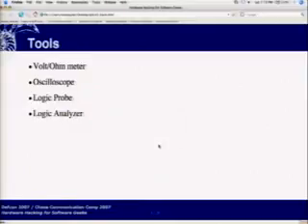So these are some basic tools that I use in doing hardware work. The voltmeter is basic. If you don't have one of these, chances are you're not really doing a lot of electronics. An oscilloscope, a little less basic, but if you get one, you will not believe how useful it is, and you'll never really remember how you lived without it. Logic probes and logic analyzers are both for working with digital logic only, and the logic analyzer is a little expensive. Logic probes are very simple. I'm going to go through these.